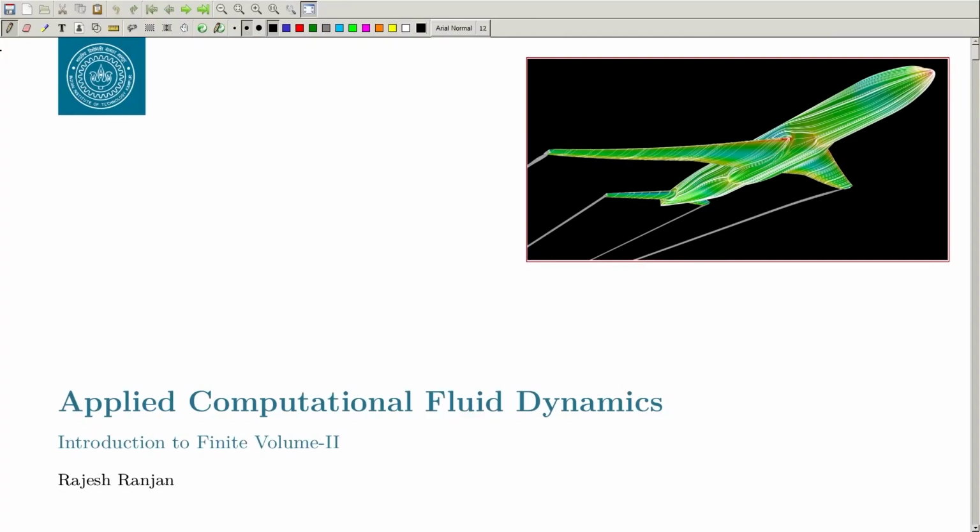We saw that as soon as we use the integral form, we can use any kind of elements that we want. In 3D it can be polyhedral, like hexahedral, tetrahedral, prisms, pyramids. In 2D it will be polygons, triangles, quadrilaterals. This gives us the flexibility to use the finite volume approach for more complicated domains. In fact, this is the approach used most commonly when the simulation domain or the geometry is quite complicated. So, let us continue the discussion.